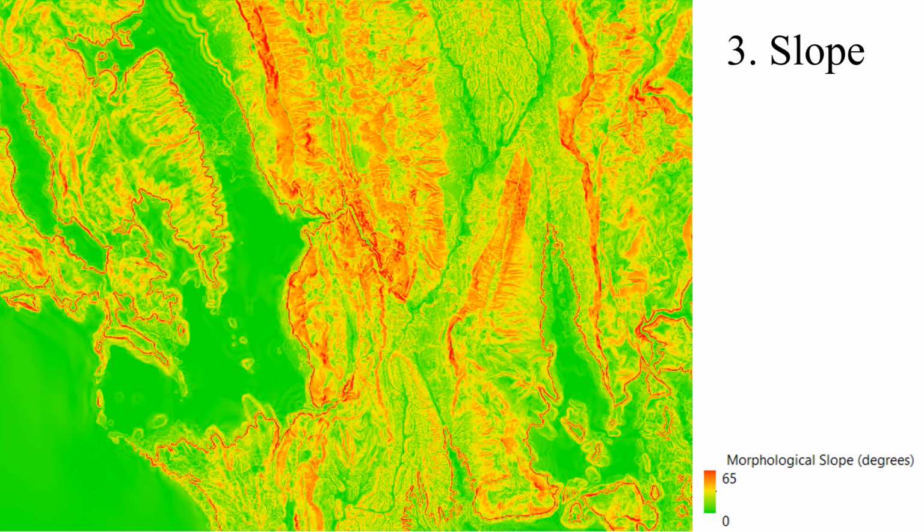For the coastal zone, the situation is similar. A decreased coastal slope renders a larger part of the coast vulnerable to wave activity, thus increasing both the risk of coastal flooding and coastal erosion.